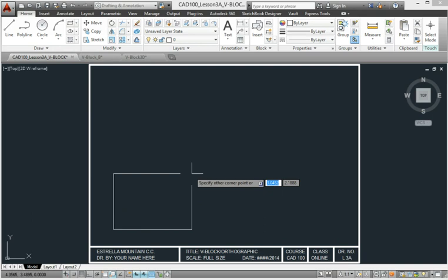To enter the width and height of the rectangle, you start with the width, what you see in blue. In this case, it's going to be 4 3/4. Hit the tab key to enter the height of the rectangle, which would be a height of 2. Enter, and we now have our front view.